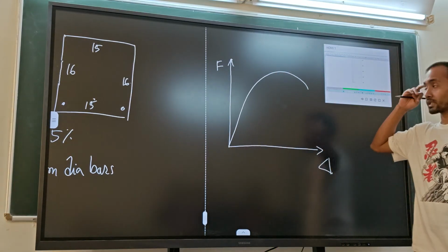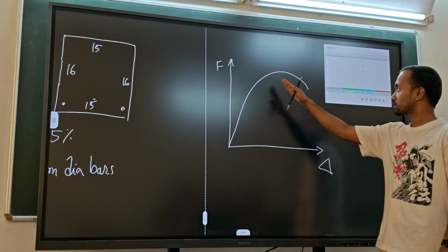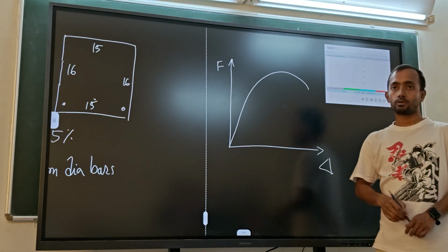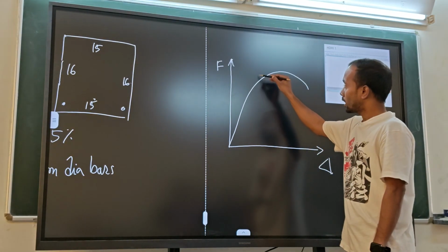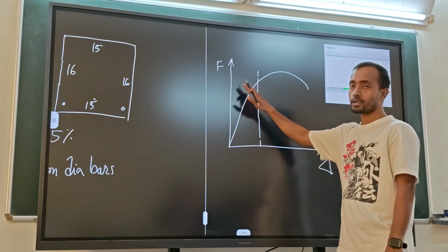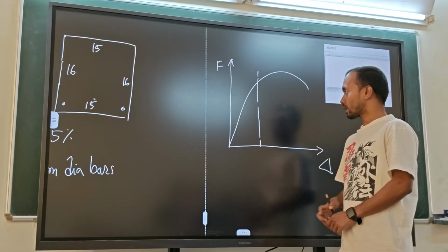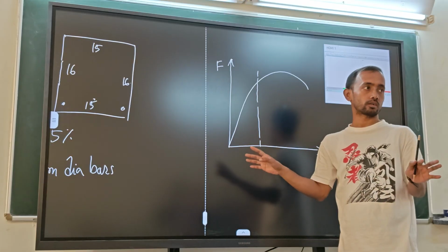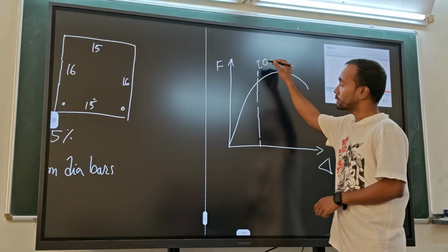Let's say this is your load displacement curve. Initially you have this linear elastic phase, then it reaches the non-linear phase, then somewhere the peak, then stiffness degradation, after that this softening. So what the codebook says, like ASCE 41 for non-linear analysis, up to a certain range beyond the linear elastic phase, if your performance is within this range, then you can use the structure, meaning occupy the structure immediately after the earthquake. There will be no threat to the occupants. So this is considered as IO, immediate occupancy.